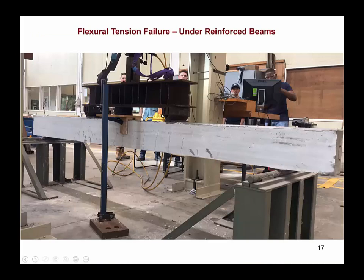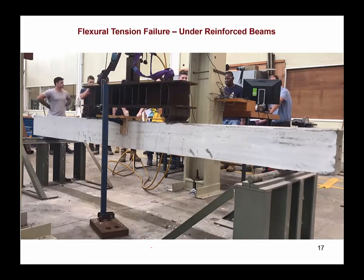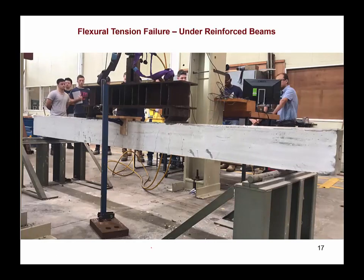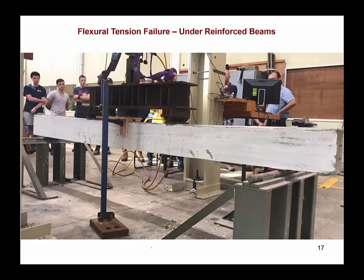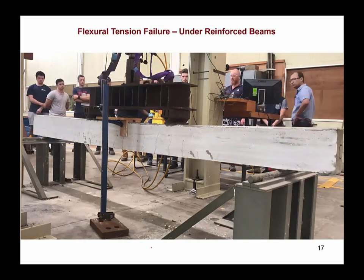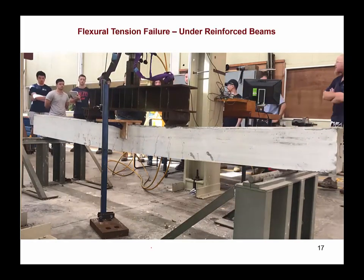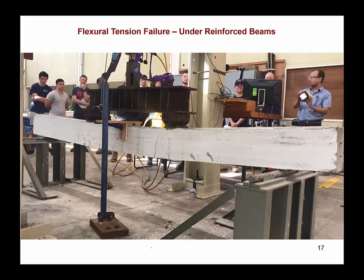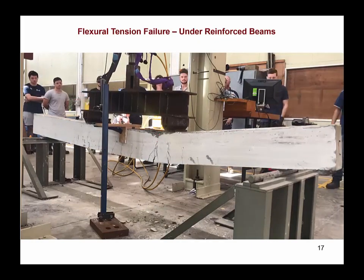Now this is the practical that we did in CS 3001, and if we can see, hopefully it will play, we'll see how ductile failure looks like. As we keep on increasing the load, we see that the cracks are starting to happen in the concrete beam in the maximum moment region, and the cracks are starting to get bigger, and perhaps the steel has started to yield at some point. We can see that the cracks are getting pretty big at this point here, and finally the concrete is starting to crush here.